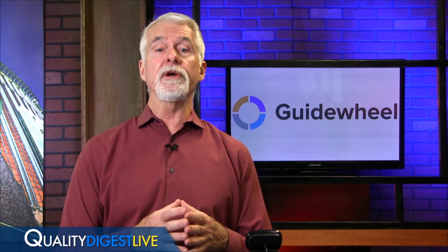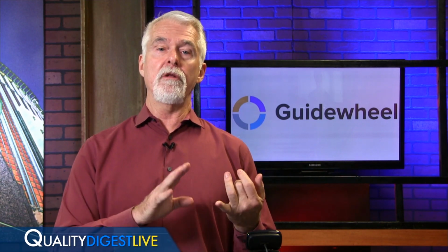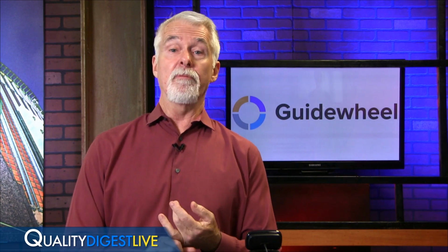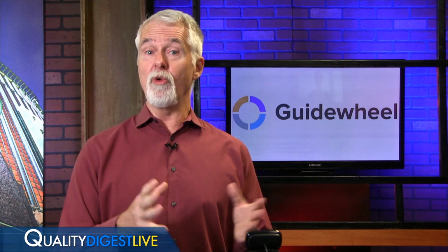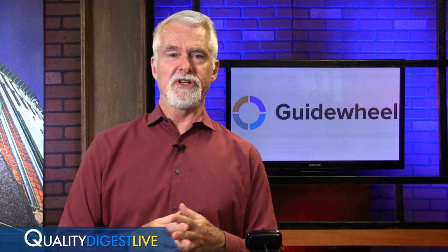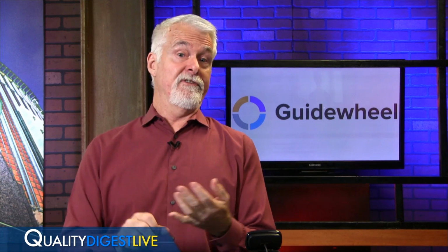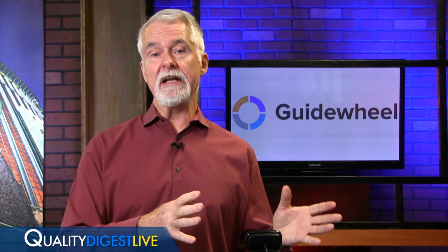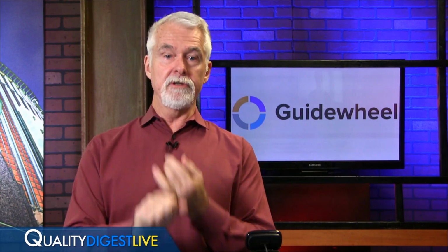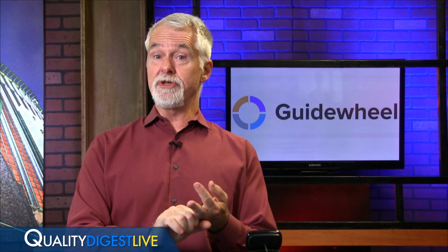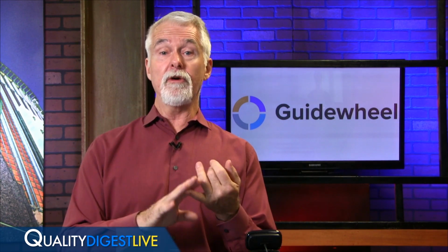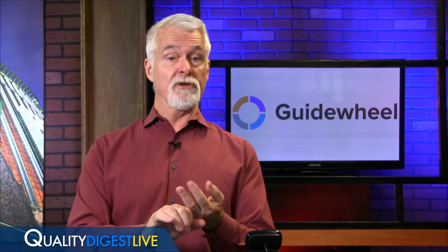And today we're going to talk a little bit about overall equipment effectiveness, OEE, what it is and a tool that can help you get a handle on it, even on your older equipment. So just briefly, overall equipment effectiveness is the percentage of available manufacturing time that is truly productive. You're cranking out good parts. You want to be producing as many good parts as possible, as quickly as possible, with little or no idle time in your process or in your equipment.